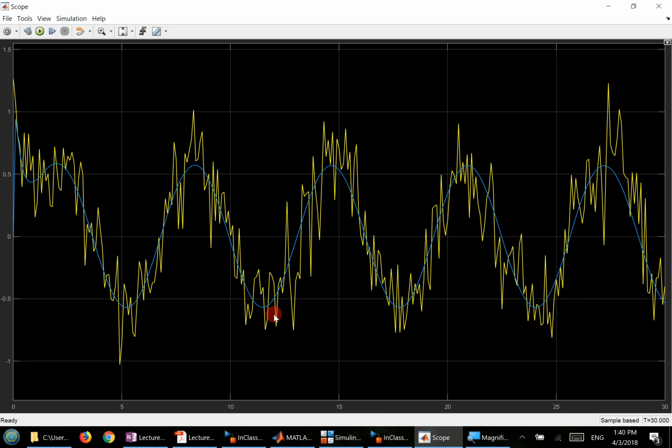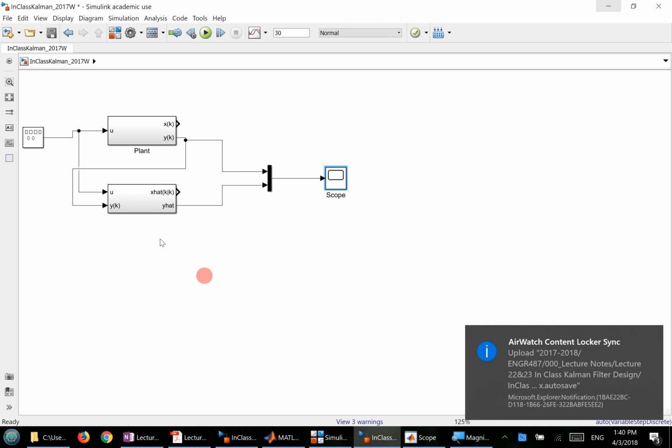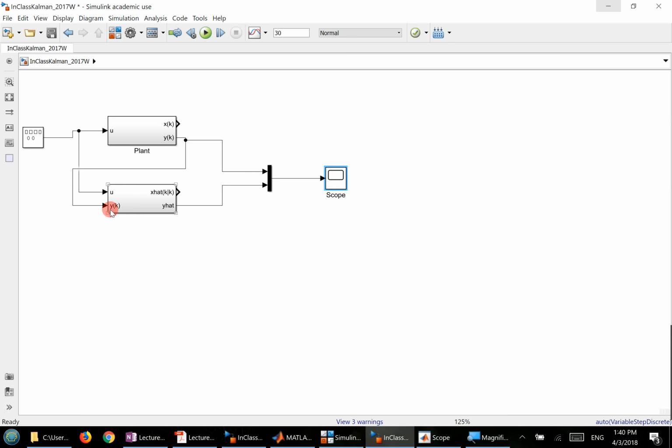The DC gain is a bit low. There's actually no control. You see here, there's no feedback. This is purely open loop. So I give my sinusoid to the system here. If you want feedback now, then instead of directly giving the sinusoid to the U, U is generated by what? You need a feedback gain here, multiplied by the Kalman filter estimate x of k, and the output of the gain is given to the U here. That's regulation, just like any other pole placement or LQR, right?